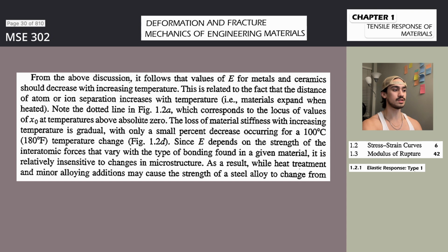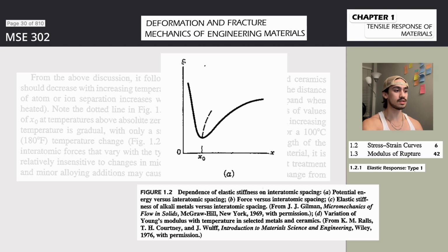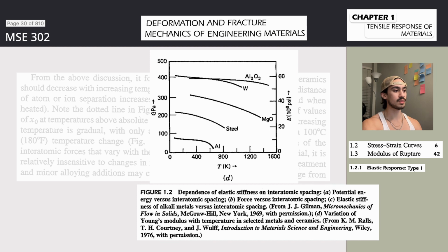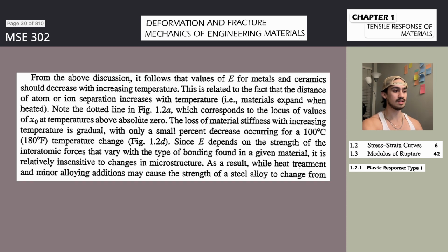For iron, we have this expression, E of 110 is equal to 210.5 gigapascals. We have some other things that would be good to look at. For example, note that E111 is greater than E110 is greater than E100, and that E110 is in good agreement with the average value of E, modulus of elasticity, for the polycrystalline sample, table 1-1.